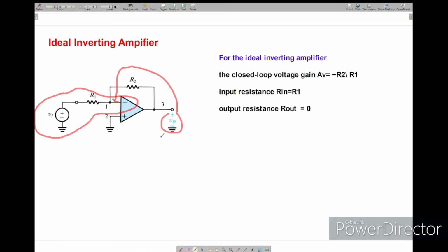In the previous lecture I explained the open loop drawback. There we can't control the stability or gain of the op amp in open loop condition. So to control the gain of the operational amplifier, we have to provide feedback, that is negative feedback. In this configuration I have provided the negative feedback through the R2 resistor. Now we will analyze this circuit to get the closed loop gain.